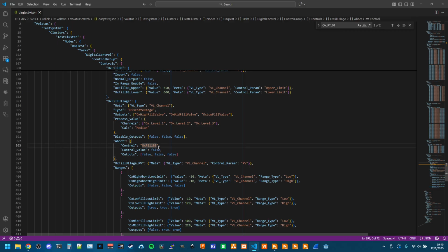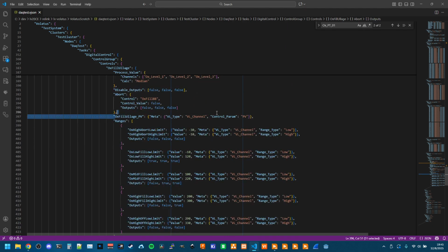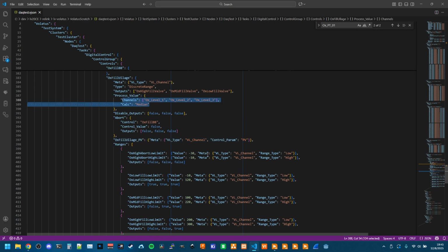But we want to turn off the bang bang so that if pressure is still fluctuating, it's not trying to turn this back on. Because if we've gotten out of one of these configured ranges, there are issues. And just make sure all the valves are closed. There's a process value telemetry channel. Again, just make sure we can see what the result of this process value selection is.